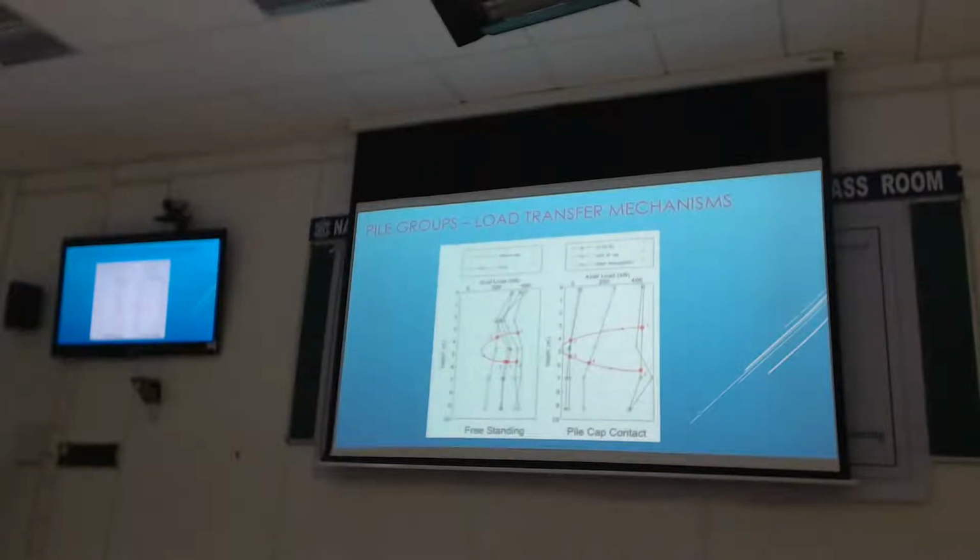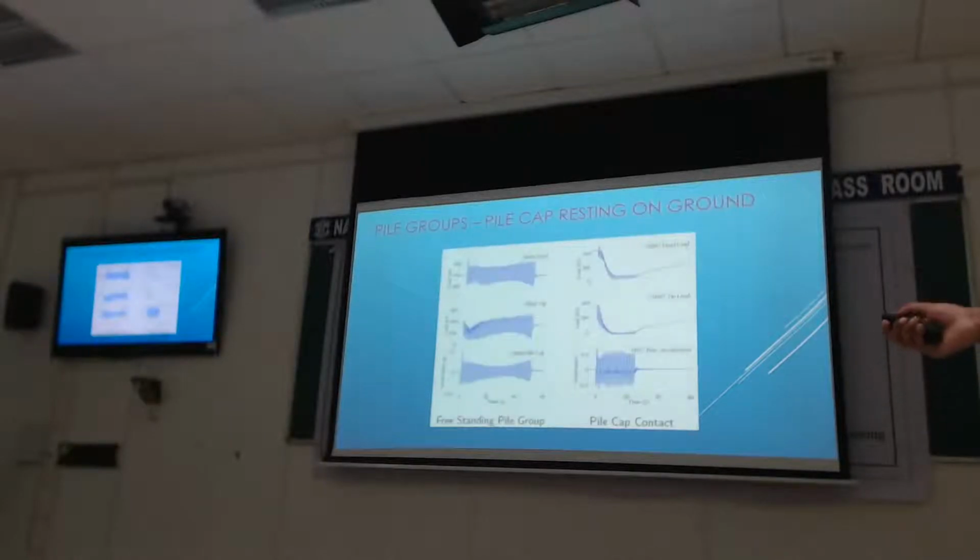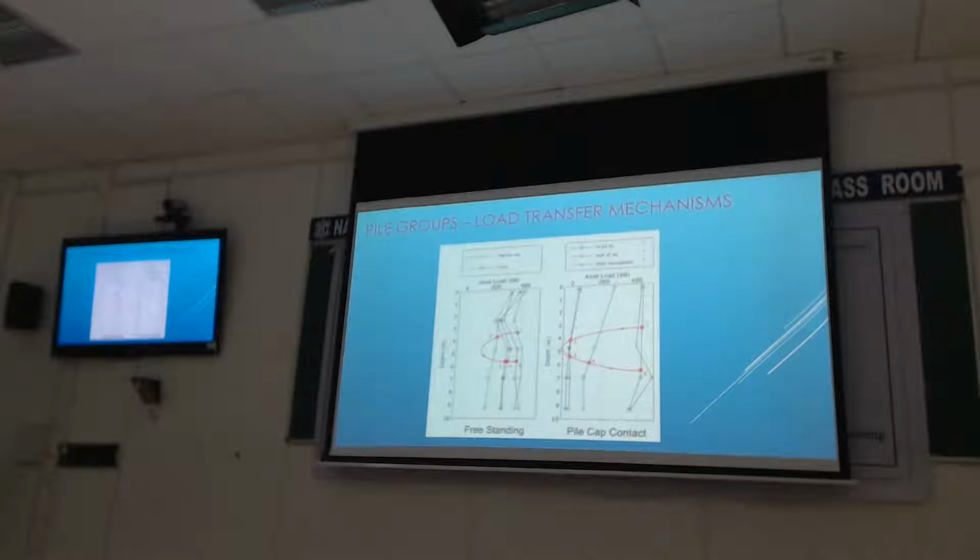And for this, you need to not just look at the top, and here we're only looking at the tip and at the head. Strain gauge A and strain gauge E. B, C, D we ignore, right? But we have the data for that. So why don't we plot the axial distribution of load with depth for both cases? And this is amazing.